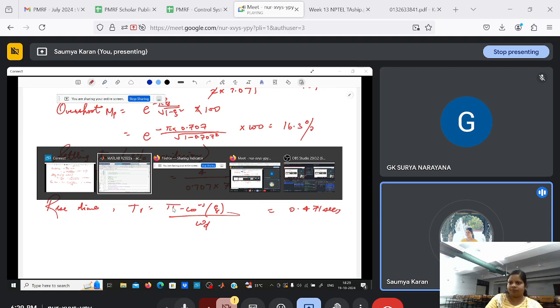Let's run this. Okay. You can see rise time to be equal to 0.304 seconds, somewhat different from our calculation. Settling time to be equal to 0.843, we calculated it to be 0.8. And overshoot is a bit different.